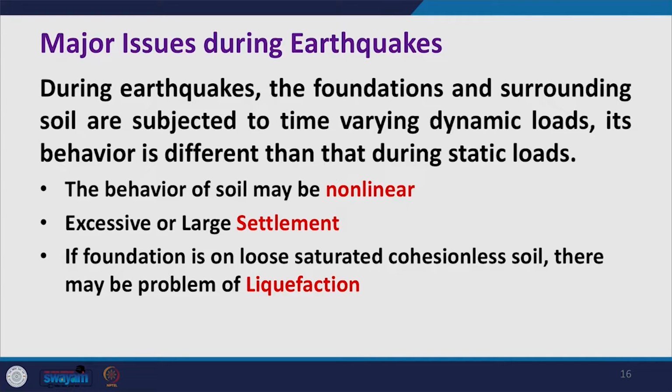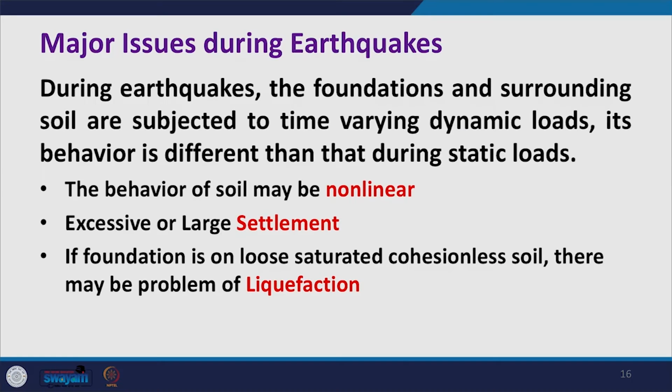First of all, during the earthquake, particularly when there is strong shaking, the behavior of soil is normally nonlinear. So, that means we need to consider the nonlinear properties of the soil in the analysis. Then there could be excessive settlement, particularly if your soil is liquefiable.